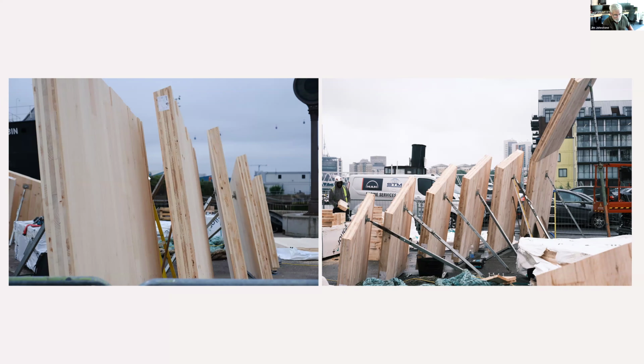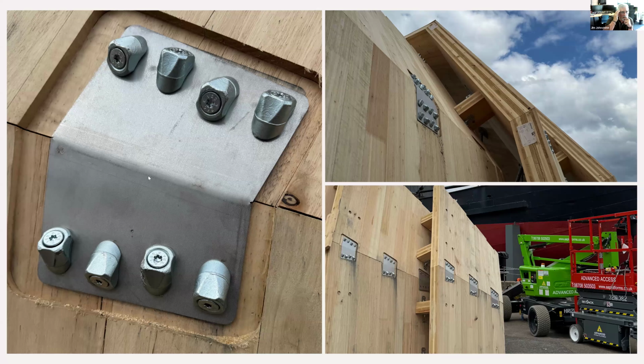Now, something I was going to mention, the screws that we used, the VGSs, there's been a comment earlier about how are they held in, how do we keep the angle? So the washer is the key to that, the 45-degree washer, and that is set within the ellipse on the plate, and that then guides the screw in on the angle that we need. There we go. That's the washer in place with the plate.